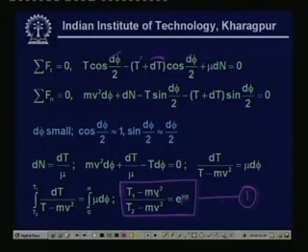So, belt speed or the pulley surface speed, tensions in the belts, the belt material property, its mass primarily, and the coefficient of friction and angle of wrap. So, everything is included in this same particular equation. So, this is one of the very important ones in the calculations of the belt drive.